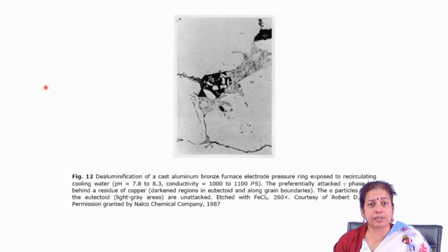So, the second type is typical selective leaching. For selective leaching, not only microstructure but composition is very important. Whenever you have an alloy system where the alloy constituents have differential leaching behavior, you have to be careful, because they may leach away, leading to porosities in the matrix. When they leach away, the component is no more continuous in nature, so there will be a lot of defects.